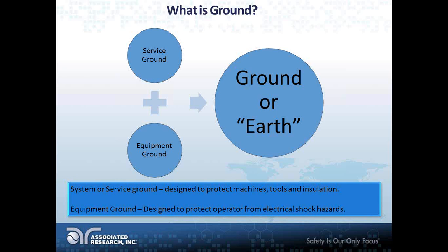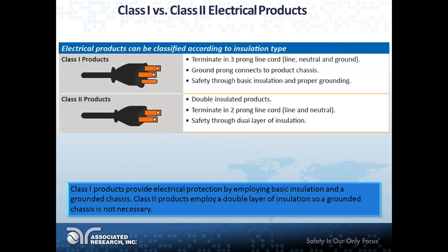So that's why it's very important. You want to reference everything at the same point because it's going to keep you safe and not cause what we call current loops or ground loops, where you have various points at different potentials. Because remember, if you have different potentials at different points, current can flow. Give it an impedance or a resistance between those points, and it's going to cause current to flow. That's the bottom line here.